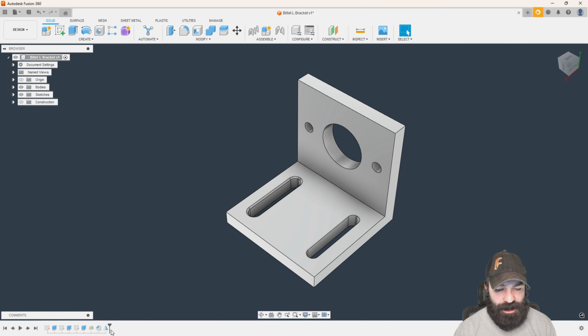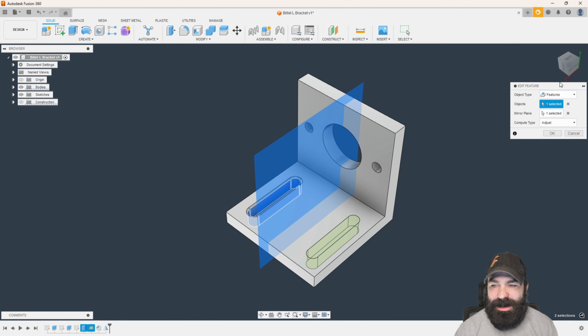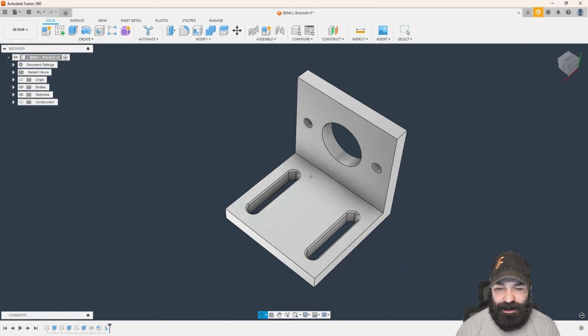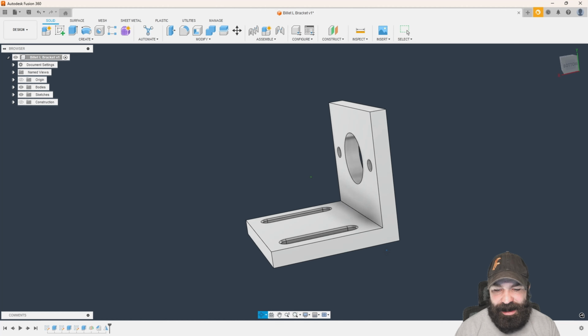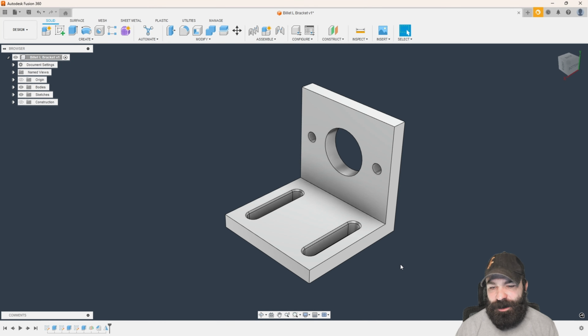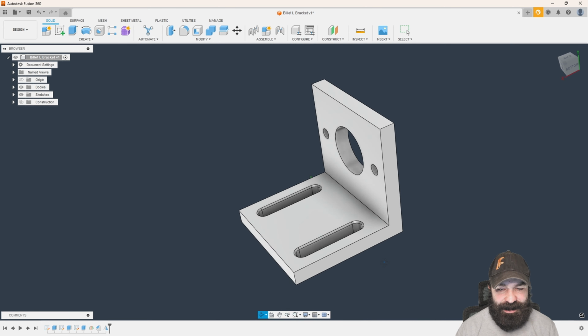So let's go ahead and fix that. I'm going to click that mirror and drag it. But now again, it's still not happening. And the reason why is because when we declared our features, we never declared the chamfer feature. So as I double click mirror, I'm going to hold Control and click that actual chamfer. Let's hit OK. And just like that, you can see I can bring more than one feature across when I mirror these things inside of my assembly.